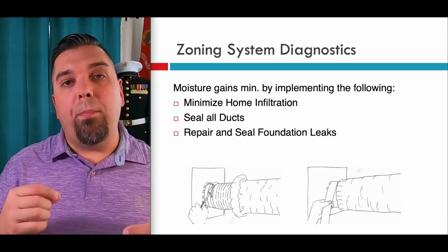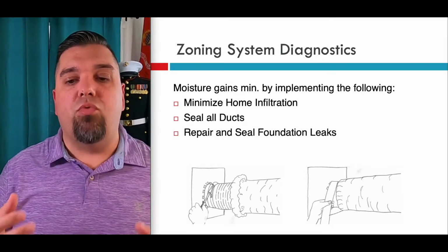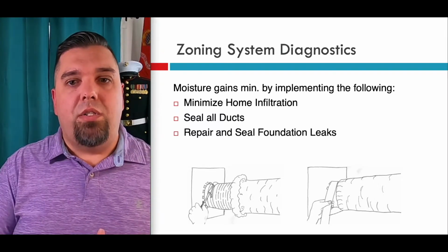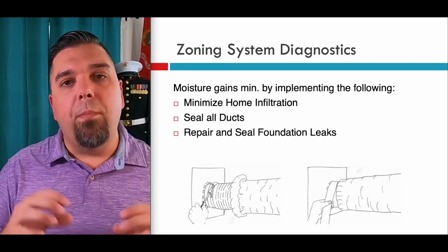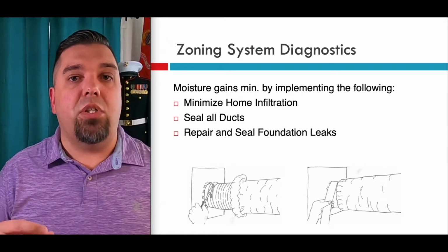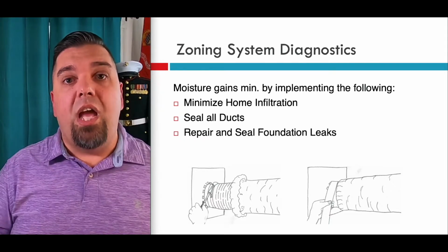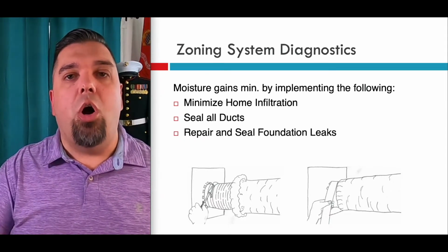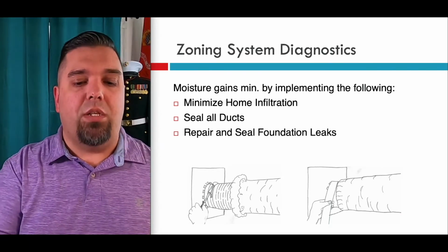But the number one place that you're going to find home leakage is around the foundation, and then of course attics, right? So all the penetrations in attics. That's where most home weatherization companies concentrate their efforts in air sealing, and you should always air seal before you insulate. Just like with ductwork, you should always air seal the ductwork before you insulate the ductwork.